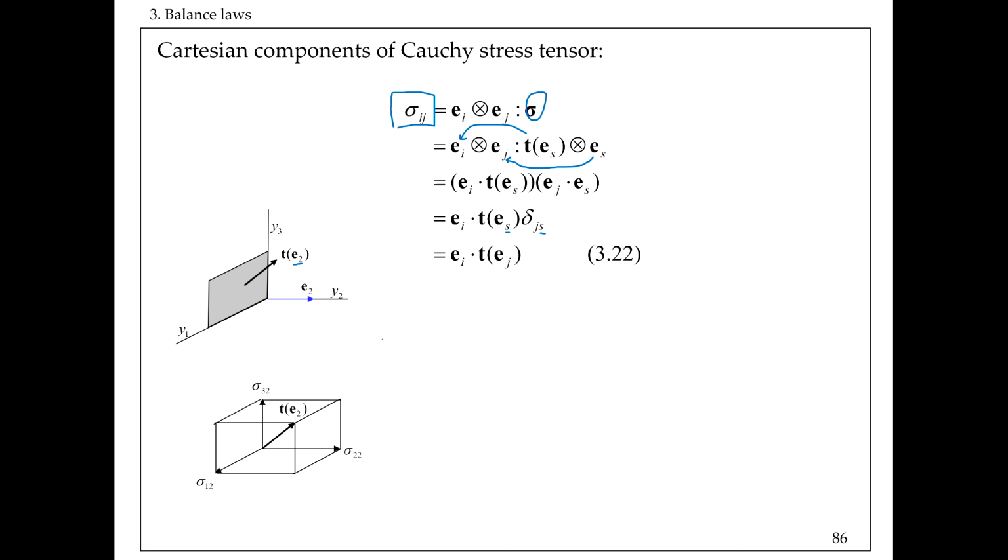So we can show this vector: the components of that traction vector will be built by the corresponding components of sigma to 2, and they are obtained by the dot product of that traction vector acting on the face that is defined by the E2 normal. So this is a normal that defines its face, and there is some traction that looks like that.